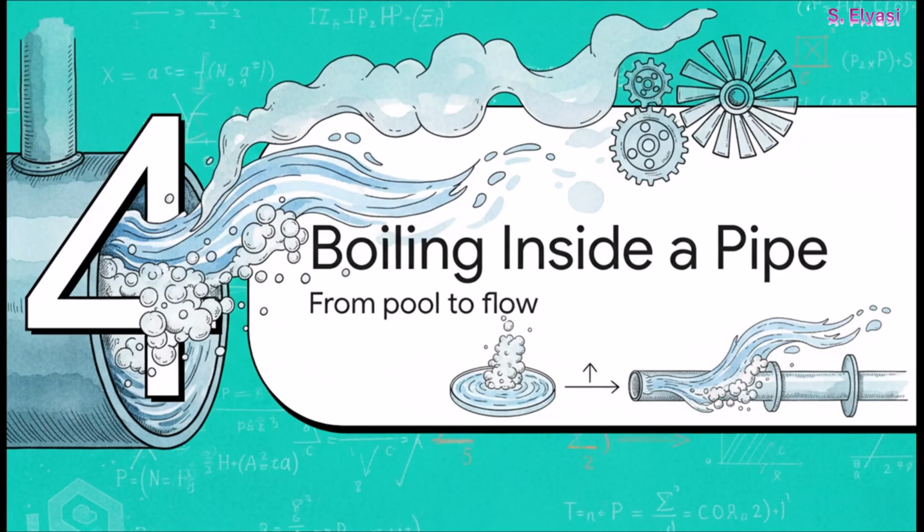Okay, so we've got a pretty good handle on boiling in a static pot of water. But in the industrial world, think power plants, chemical reactors, you're usually dealing with something way more dynamic. A fluid that's boiling while it's flowing through a pipe. This is called forced convection boiling. And yep, you guessed it, it needs a totally different formula.